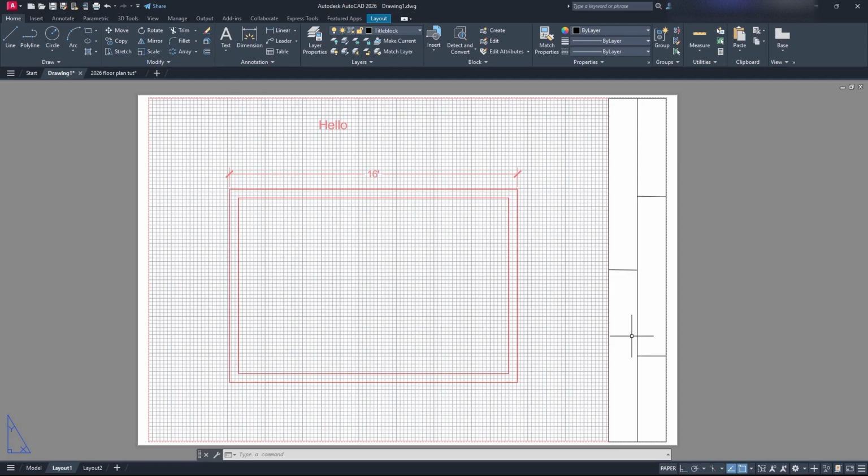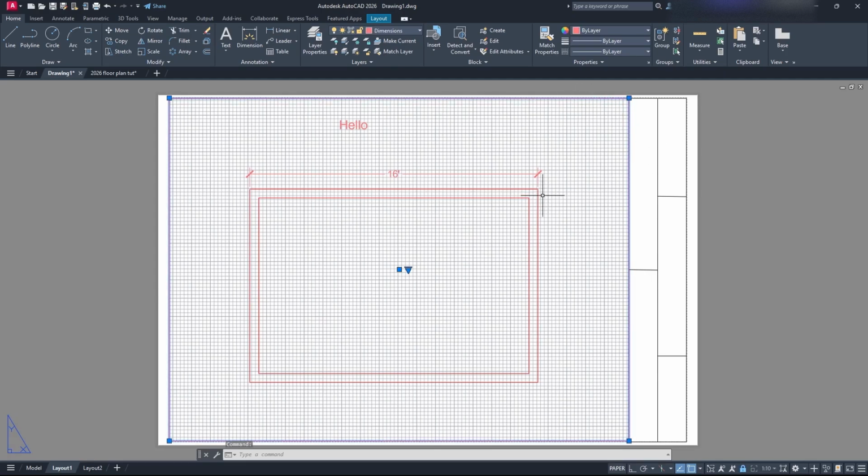There are other videos on creating title blocks, but I'm not going to go over that. Maybe I will actually make a segment on title blocks, but you'll know later on. So you make your title block, you put it here, and then you'll have it printed. That's how you would deal with your layouts as quickly as possible in AutoCAD. Again, make sure your viewport is scaled properly, it's selected properly, it's locked in place. You're going to want your title block on the side with all the information that you need, and then you'll be good to go.